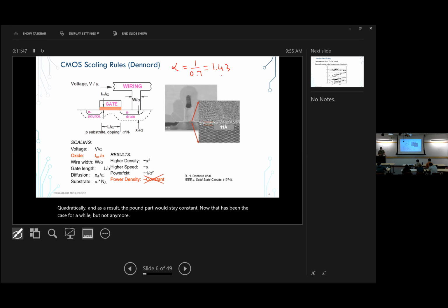One of the fundamental reasons, if you read Dennard's paper, where the end of scaling would be, he identified it as the limit to the shrinkage of the gate oxide and identified gate tunneling as a problem. It looked like something that was threatening scaling for a while, but we got away with that. And we essentially had to move to high-K dielectrics.